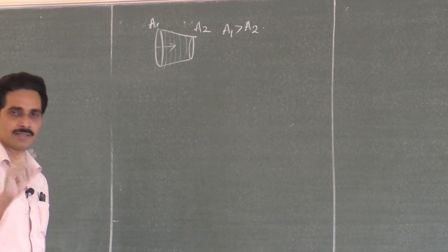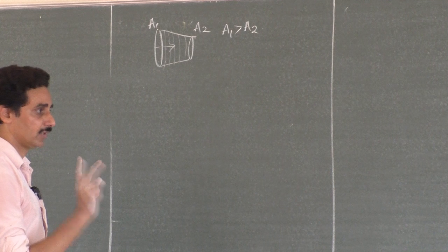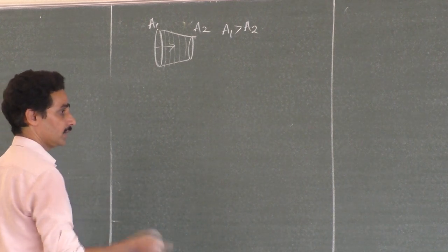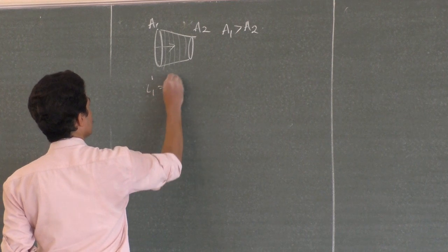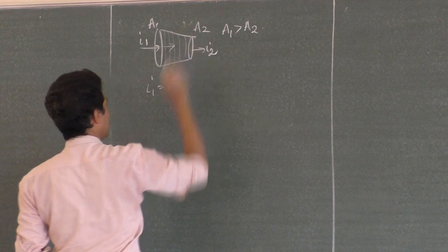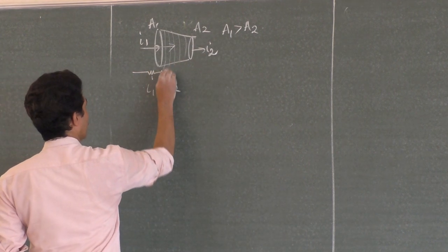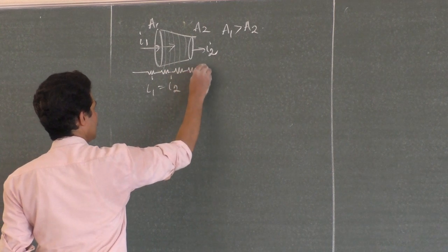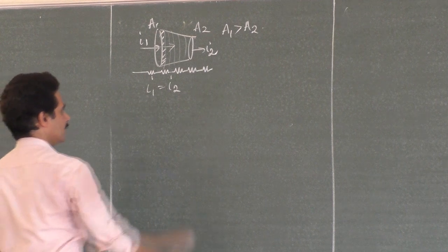So, either you can go for second option or, okay, you need not go to the question now. There is a second option and fourth option, I1 equal to I2. Only two options carry I1 equal to I2. Other options, I1 greater than I2, I1 less than I2 and so on. So, I1 must be equal to I2. If current entering is I1 and current leaving is I2, that must be same, because in series, so I can write this as equivalent to a number of resistors connected in series like this. Each slice has a resistance. So, in series current should be same.